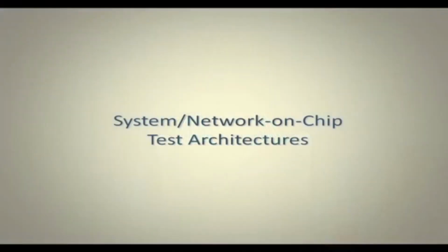After we have seen this wrapper design P1500 or the IEEE 1500 standard and all that, the next step is to look into the system on chip and network on chip test architectures. System on chip is a design style in which we fabricate the entire system on a single silicon wafer, and in network on chip, this communication problem that we get in today's ICs is addressed by introducing some sort of on chip network to which these individual functional modules can be connected. Naturally, testing issues become more important, more severe in both cases.